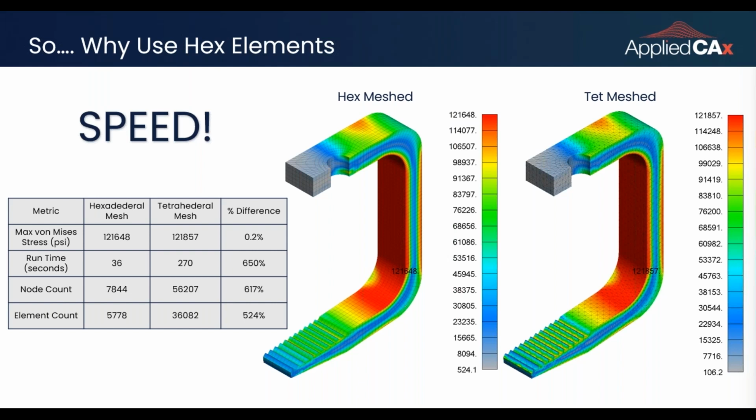So we encourage you to explore this tool and try it out. It could really save you some time. I think the geometry we see here on screen would probably hex mesh quite cleanly with the auto hybrid mesher. But I've seen plenty of others that I would just rather use a tet mesh, knowing that I have a consistent element type and no transition regions in areas of concern. So use some of the knowledge covered in this seminar to scrutinize the mesh that those automatic tools can give you. But that being said, it does have its advantages in terms of creating things quickly.